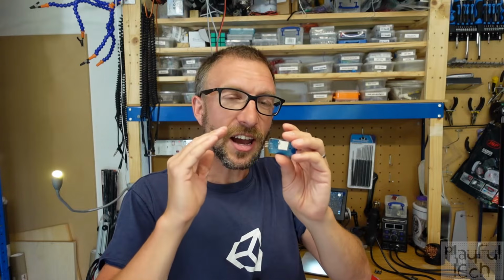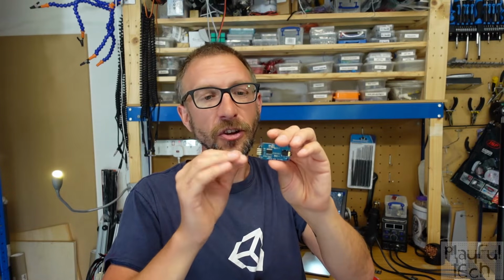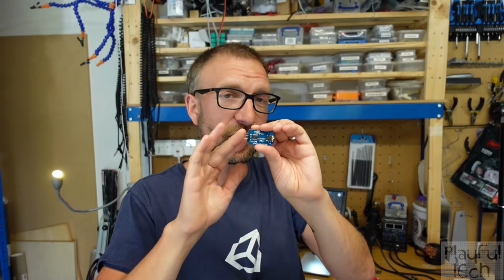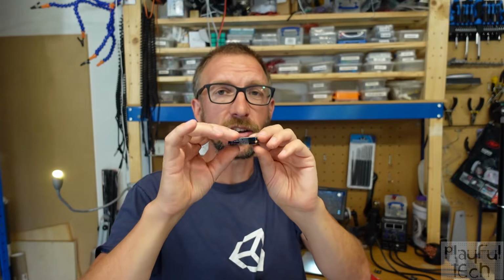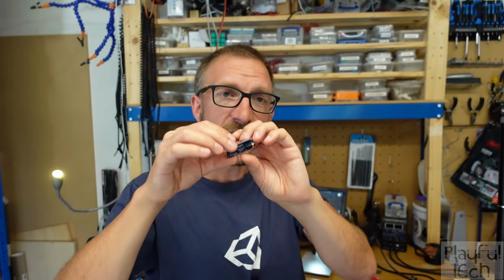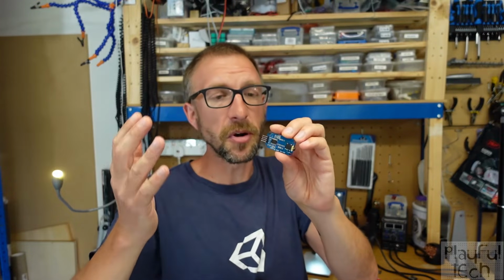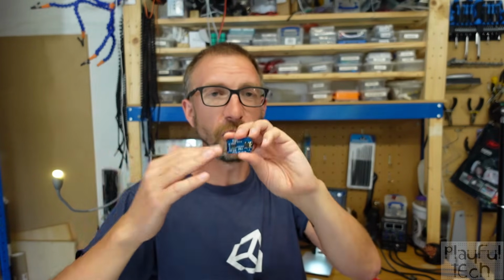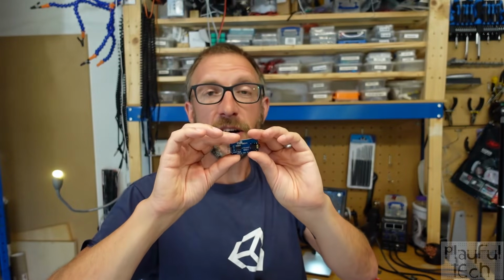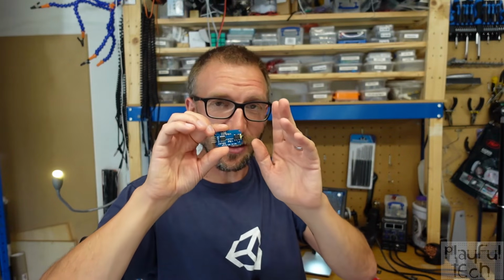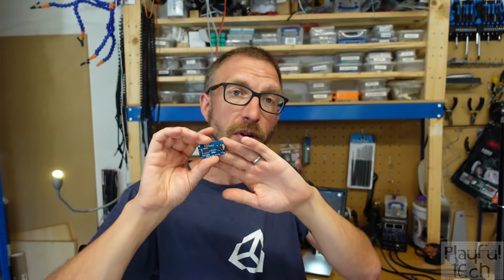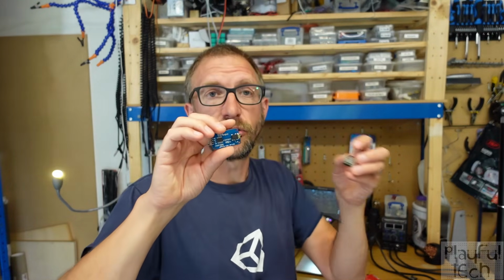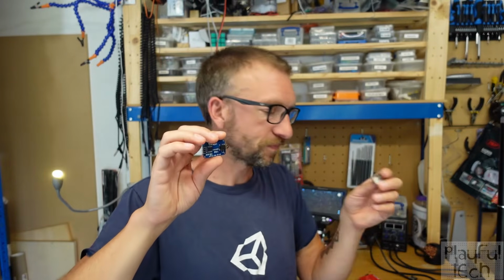It also doesn't have any I/O pins, so you can't use this as a standalone device. The only way you can control playback of audio from the SD card here is through the serial interface from a microprocessor like an Arduino or Raspberry Pi. Now, the commands that the chip understands are exactly the same as used by the DF Player, so you can use the same Arduino libraries to control either of these devices.